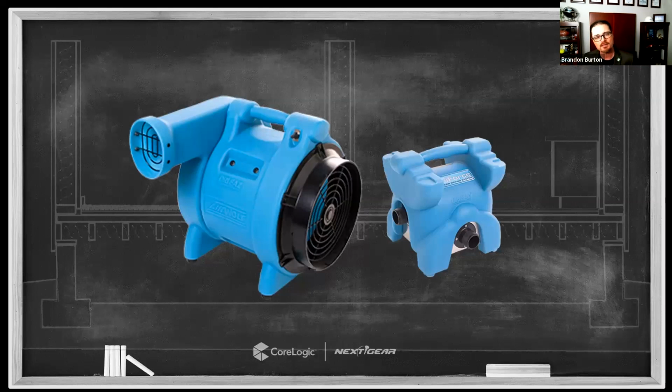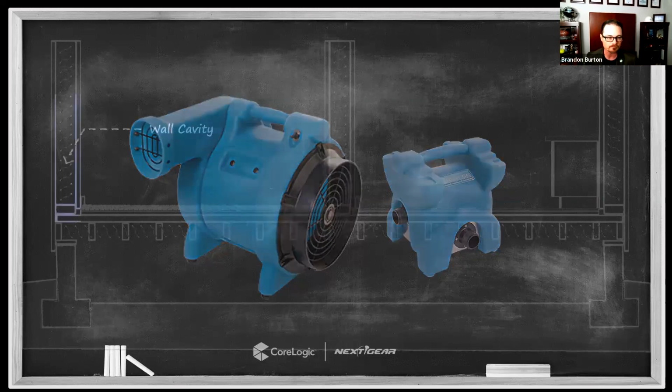The variety of these systems are all a different balance between the amount of air they produce and the pressure that they're capable of producing behind that airflow. All right, so it's a balance between the two. And generally, those that produce more air don't have quite as much pressure. And those that have a whole lot of pressure to force it through really tight spaces, well, they don't produce a lot of air. So it's usually a balance between these two, okay? If we had a whole lot of both, then you would need a 230-volt power source to run the air mover. So it's got to be kind of a balance between the two.